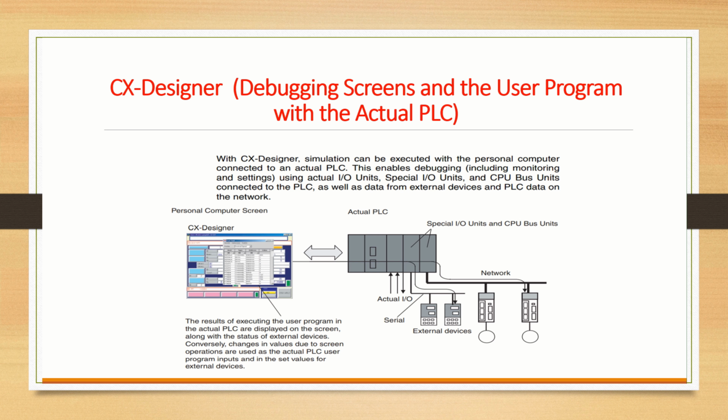With the CX Designer, simulations can also be executed with the personal computer connected to an actual PLC. This enables debugging using the actual input-output units and the CPU bus units connected to the PLC, as well as data from the external devices in the PLC data on the network.